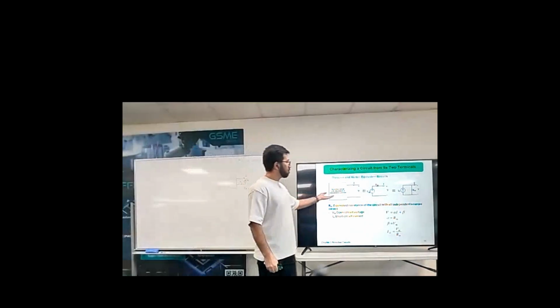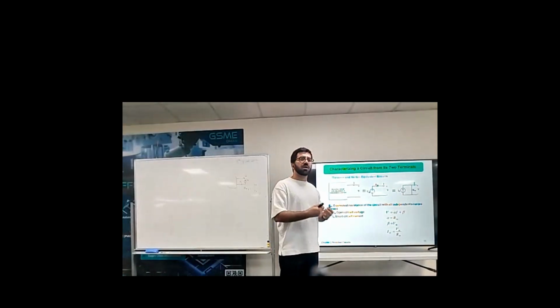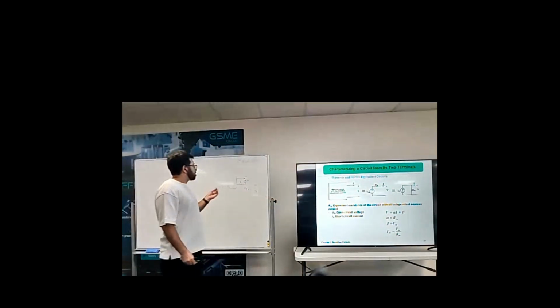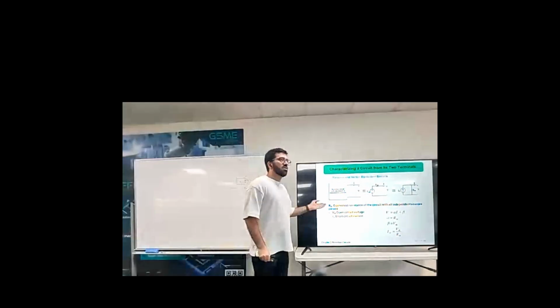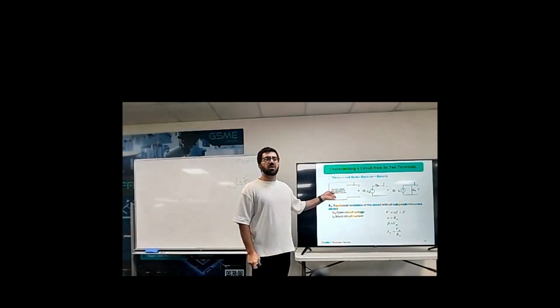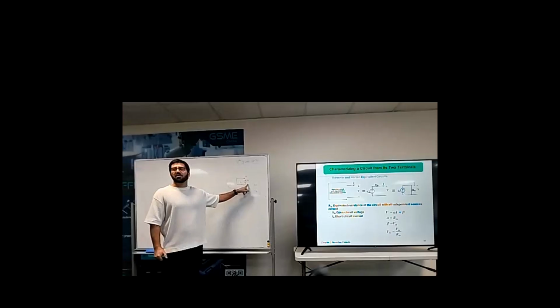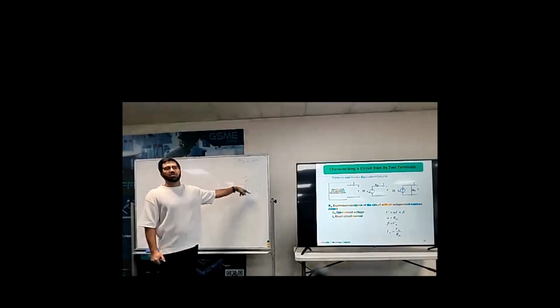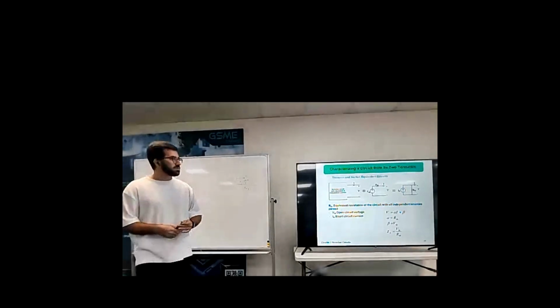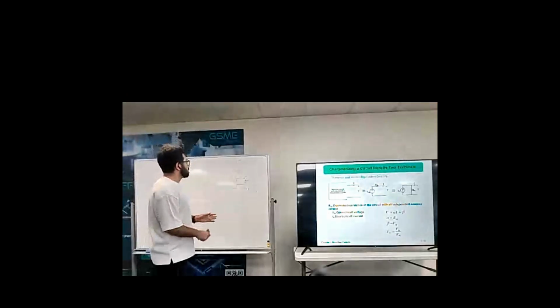Sometimes it's easier for you to just simplify the circuit by paralleling and series the resistors. If we have dependent sources, what do you do if there is a dependent source? Can I use parallel and series to find? No. If we have dependent source, we should apply VT and find the relationship between VT and IT. That's the general method to find equivalent circuit.